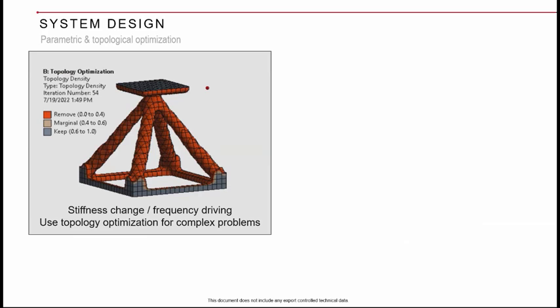Then you can explore the latest analysis tools that you have. For example, topology optimization. This is for some fixture. I am just trying to show some random example. You can try to get the best layout of mass and stiffness distribution for your designs and utilize it for optimized versions as well as for the frequency that you intended to have.